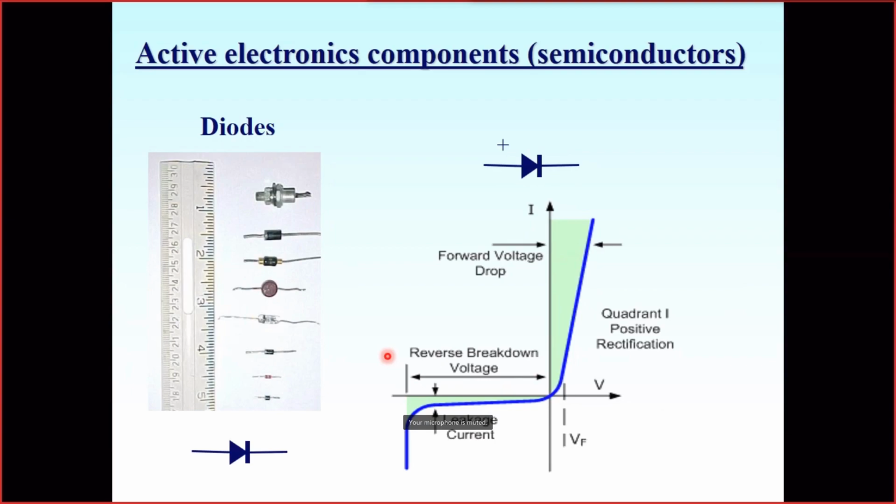And there are diodes which are designed to emit light. Generally, every diode, when it's switched on at forward voltage drop, emits some light, but this light usually remains inside the diode. If you speak about germanium or silicon diodes, this light will be in the infrared region. We don't see it. Other types of materials like gallium arsenide, gallium phosphide, and so on, and even more complicated ones with three metals inside, are often used to make such light emitting diodes in the visible range.